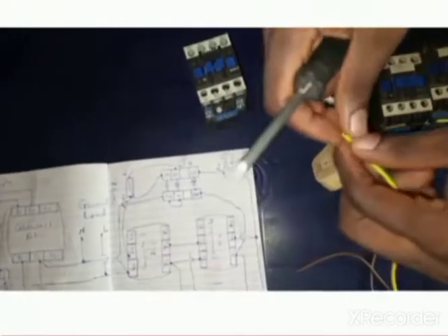Alright, looking at the diagram, you see that we have to connect using this diagram. The live wire, I'm starting from this utility supply. The live wire from the source connects to L1 of contactor 1, and connects to 2 of the pin relay. This is pin relay 1, an 8-pin relay, and from 2 connects to 1 of the pin relay. So I'm using this as supply 1, which is the utility supply.